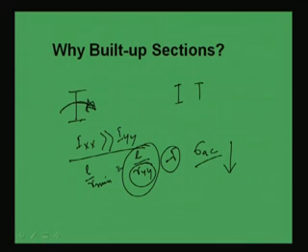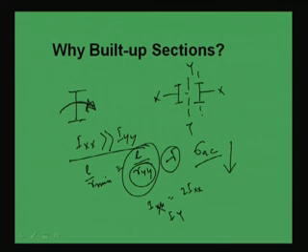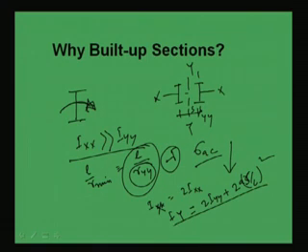That can be made if, in place of a heavier section, we arrange sections like this. Then the equivalent Ix will be simply 2 Ixx, but the equivalent Iy, if this is x and this is y, will be 2 Iyy plus 2 A r square. Here r square, if this is S, can be written as S by 2 whole square. In this way the magnitude of Iy is increased.